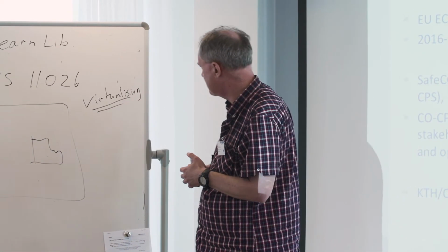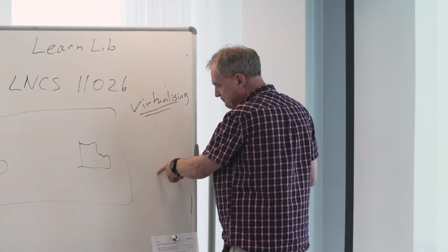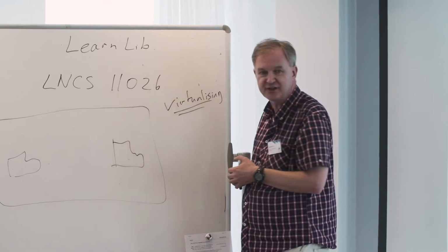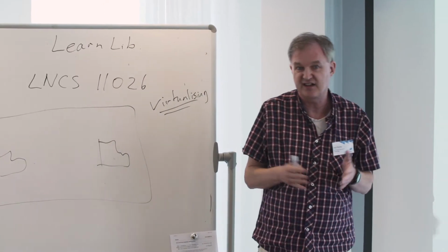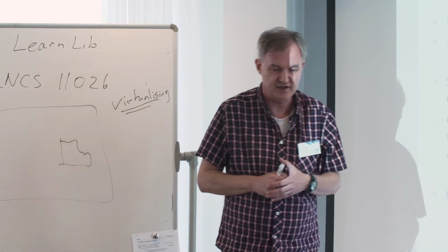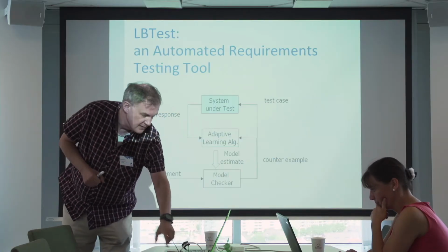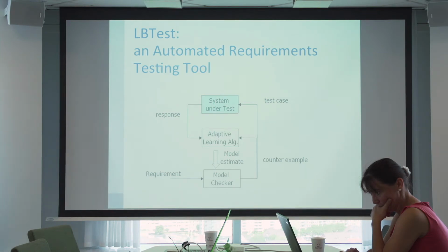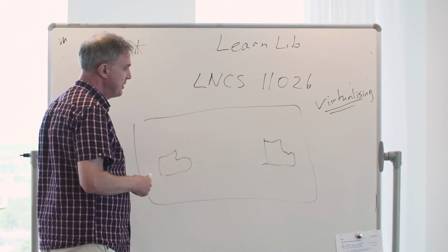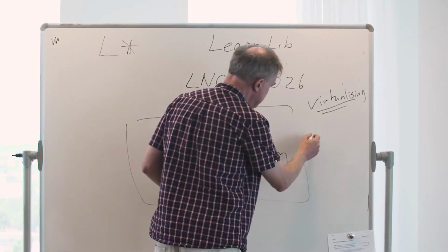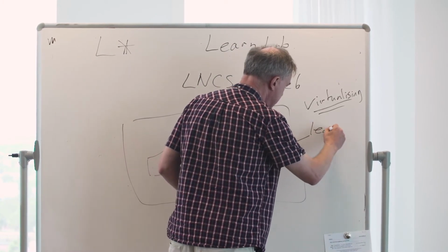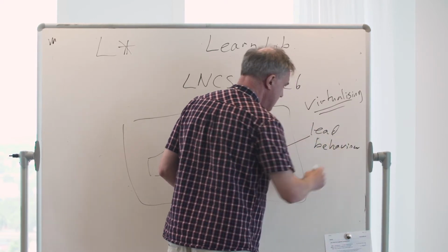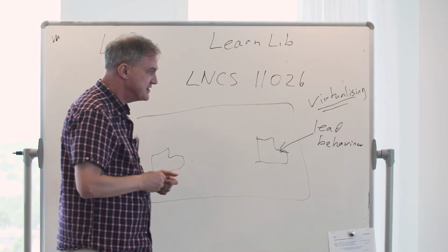It's a very productive way to go, because if you have simulators, it's much quicker to clone a simulation than it is to physically clone another mechanical truck, right? It costs you a hell of a lot less. In fact, it costs you nothing if you have a site license. So we're going to look at evaluating the safety of a distributed algorithm inside an entire platoon. And what we're going to do is simply stimulate the lead driver behavior. Okay, so those are our in signals. That's the main in signals.